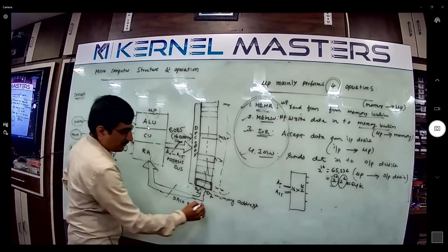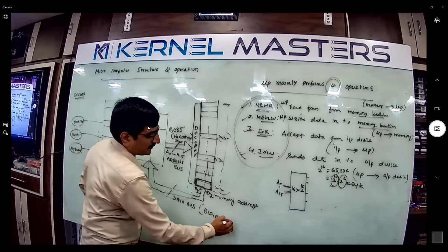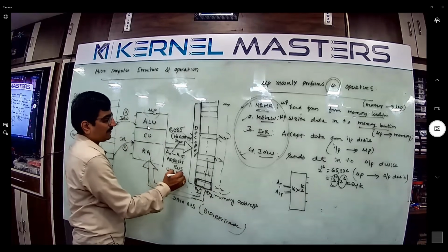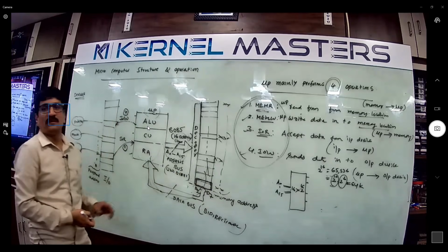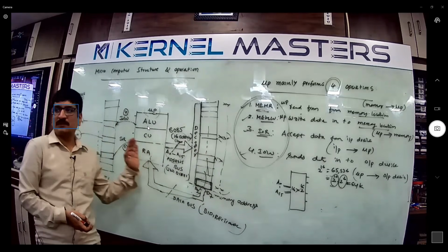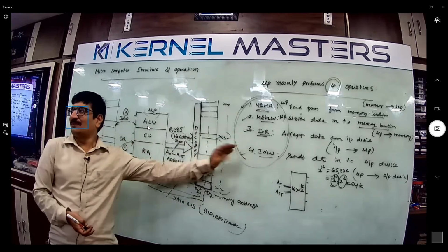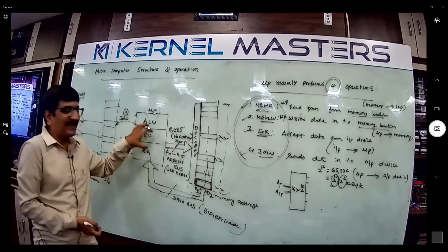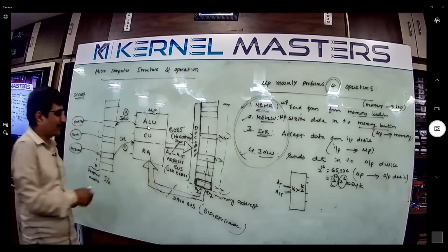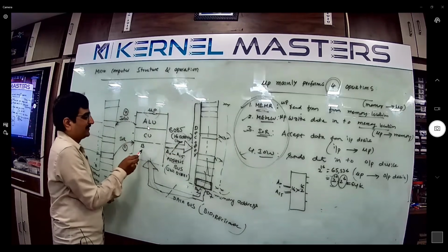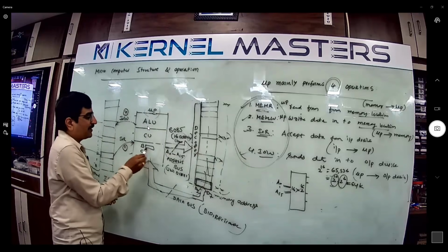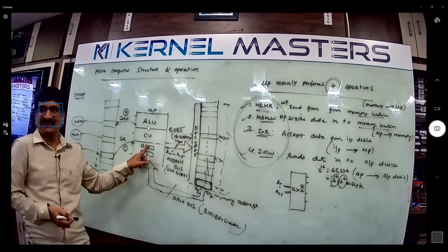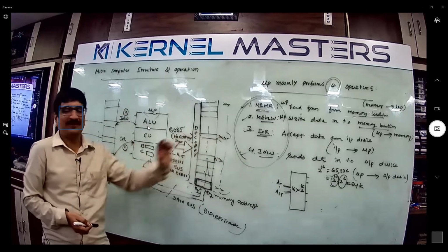The data bus is bidirectional. The address bus is unidirectional: from the microprocessor only to the memory. The memory does not need to address the microprocessor. The microprocessor also contains registers, like the B register and C register, but these registers have no addresses, because the memory does not communicate to the microprocessor. The microprocessor only communicates with the memory.